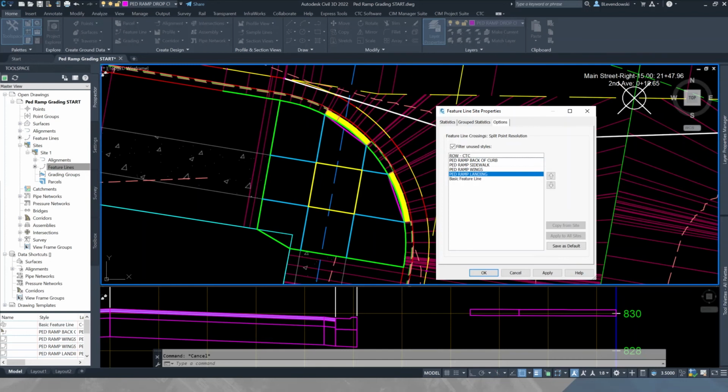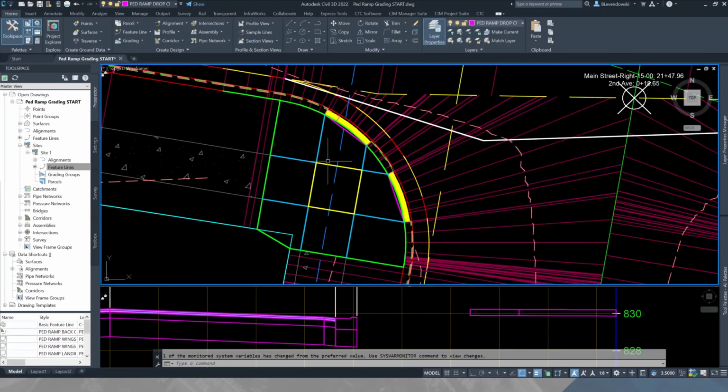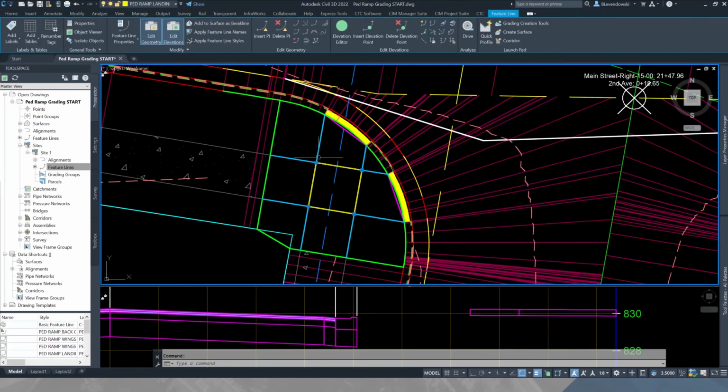Okay, so I've built a cascading set of controls here at all these different crossings, and I've intentionally crossed these feature lines and made them separate. In fact, we made this inside one a separate feature line so that it could basically be pushed up and down by all of these blue wing feature lines.